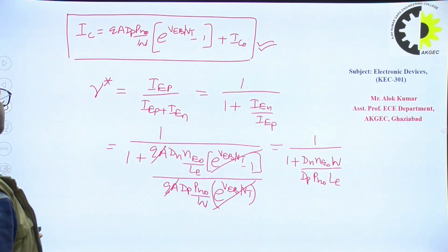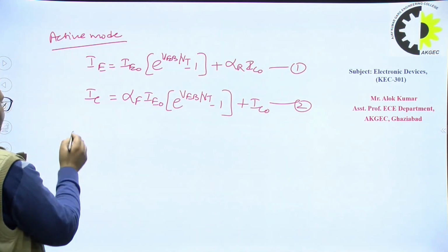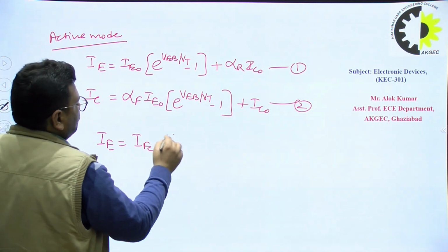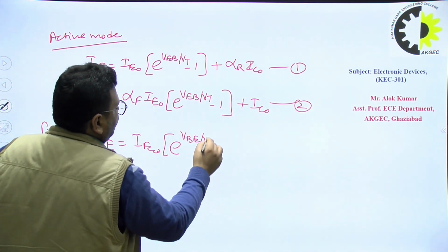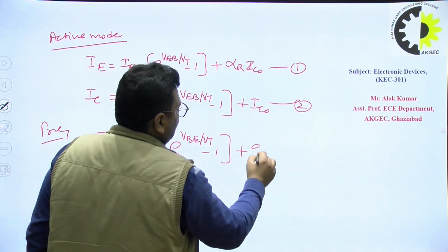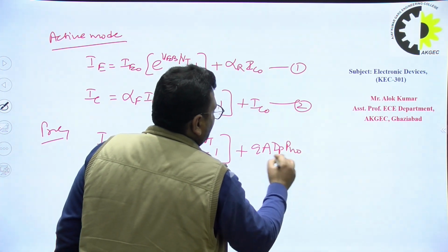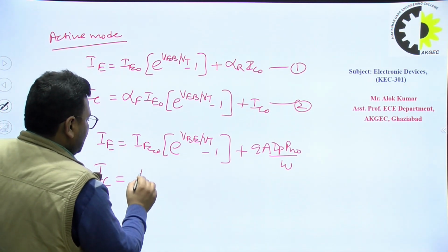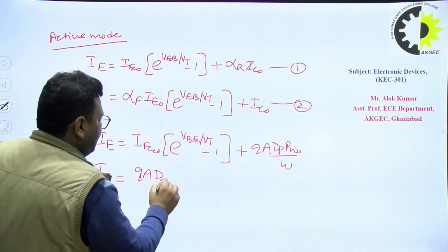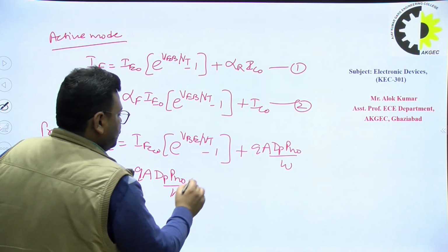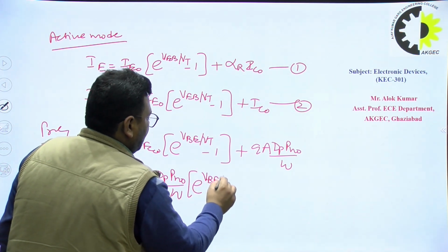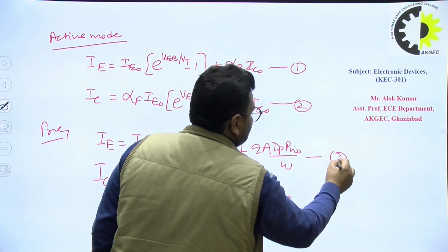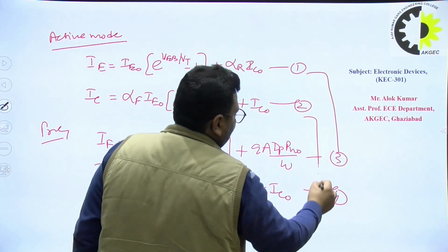So previously we obtained IE as IE naught into e to the power VEB over VT minus 1 plus QA dP Pn naught upon W, and similarly IC was QA dP Pn naught upon W into e to the power VEB upon VT minus 1 plus IC naught. If we compare 1 with 3 and 2 with 4...